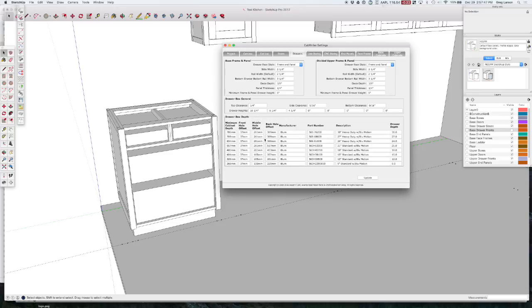So the other information that we have here is we're letting you put in various drawer slide information in this chart here. The important part here is the minimum cabinet depth for this particular slide, because that's going to allow us to choose the appropriate drawer box length for the cabinet that you drew. So this is all in metric. It can be in regular imperial measurements as well. Don't forget, if you're ever putting in metric, that there's no space between the number and the mm.